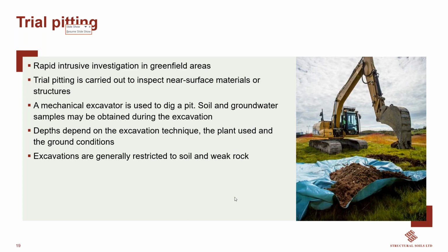It is a fantastic method. However, once we hit rock, that is it. It won't go through the rock. So again, we just need to make sure that we are looking at the geology before we go to site, to make sure that we have enough depth so we can use the excavator.